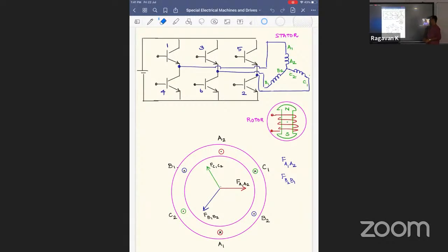Okay. Now what we have to do: the rotor MMF is continuously traveling in space, because the electromagnet sitting in the rotor is continuously traveling in space. Now, when the rotor is continuously traveling, we have to decide where the armature MMF should be, whether it should be at 30 degrees, 90 degrees. It is fixed: 30 degrees, 90 degrees, 150 degrees, whatever we said earlier is fixed. That's clear, right? Because we are also giving a constant 1 ampere current, so that is going to be fixed.